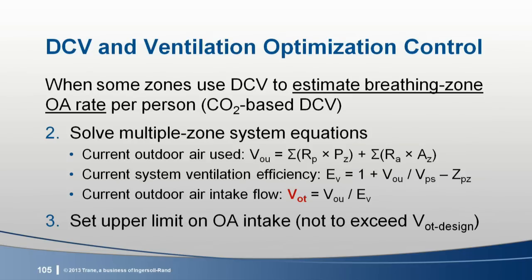And finally, set an upper limit on intake airflow. Calculations based on estimates can't result in a current intake airflow that exceeds the design value. After all, cooling and heating capacity are based on design outdoor airflow rates.